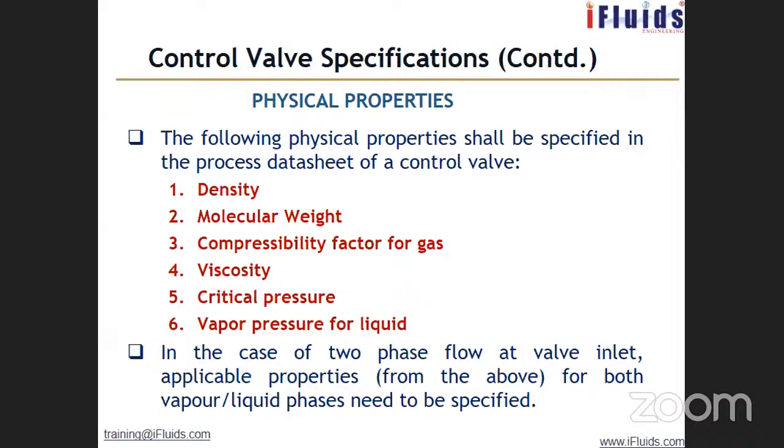Sometimes what happens, the valve also undergoes some pressure drop. Sometimes it may vaporize downstream of the valve, the liquid may vaporize. If your pressure drop is bringing the pressure of the fluid to its vapor pressure, then it will vaporize.